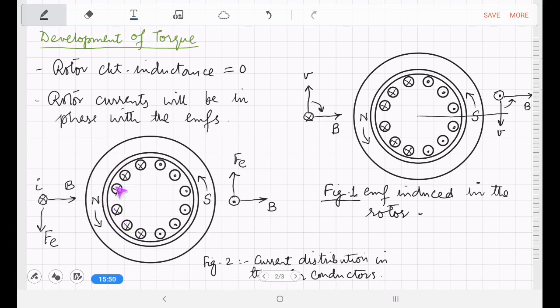in clockwise direction relative to the rotor, and hence the direction of the induced EMF in the conductors will reverse and the direction of currents too will reverse, meaning thereby that the direction of the induced torque will be in the clockwise direction. We can conclude that the torque is developed in the direction of the rotating magnetic field relative to the rotor, or in other words, the torque is developed in a direction that would push the rotor speed to be close to the synchronous speed.